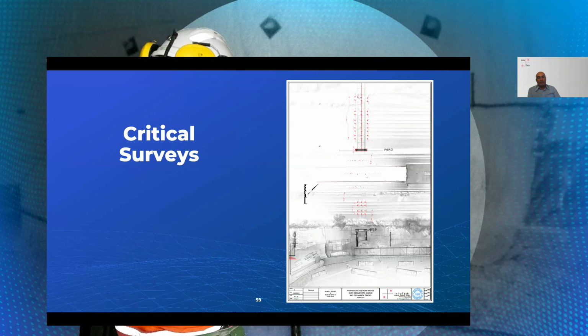Again, you're taking only one shot for that ground survey. You're taking a shot at every 15 feet, at every 20 feet, because anything else would not be realistic. But with the GeoSlam or with the 3D scanner, you can see really the shape of things that you're dealing with. So that was a very critical one.